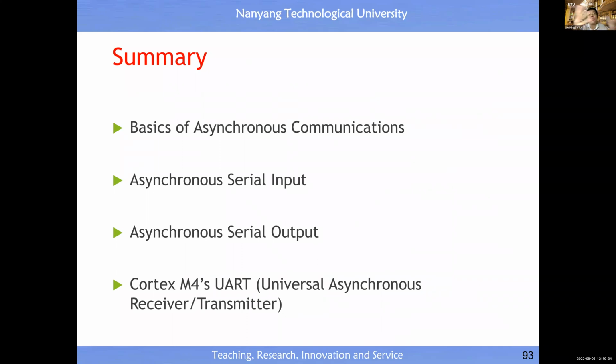In lecture 3, you know the working principle of doing asynchronous communication. Basically we use a software solution to achieve synchronization at the byte level, and the benefit of doing so is to reduce the hardware cost by 75%. That is a tremendous benefit. And the good news for you is all the microcontrollers support the implementation of asynchronous communication. Then we went through the example of a Cortex M4 microcontroller, to let you know how to use it.